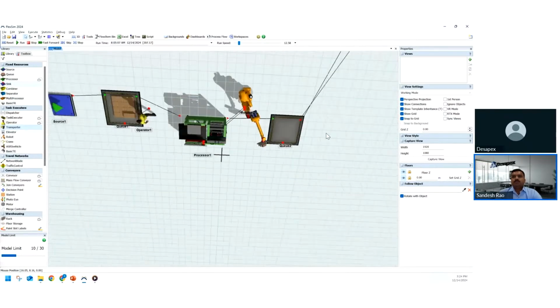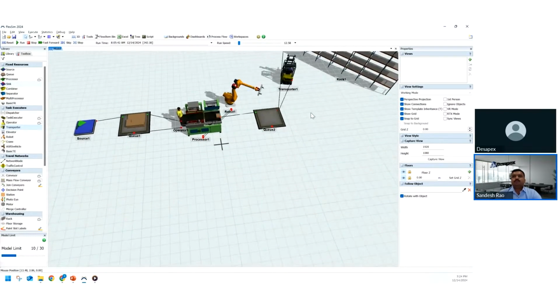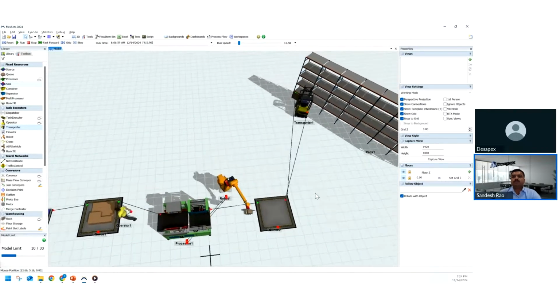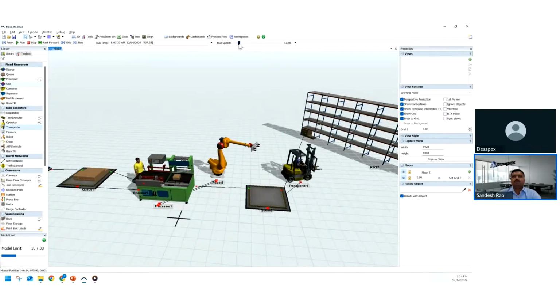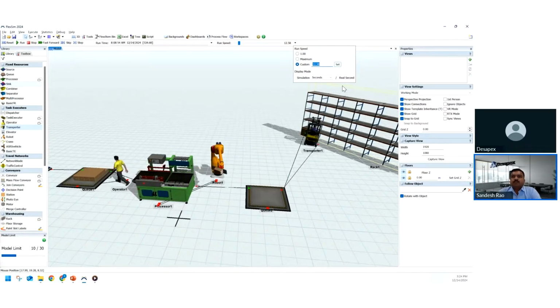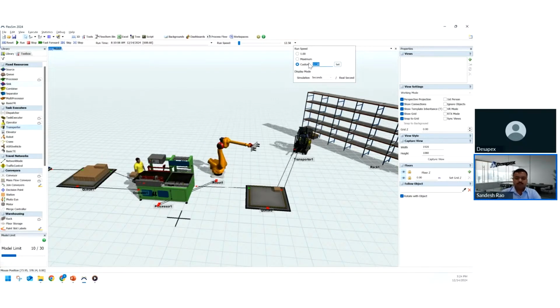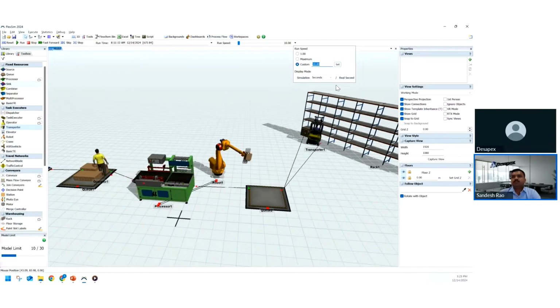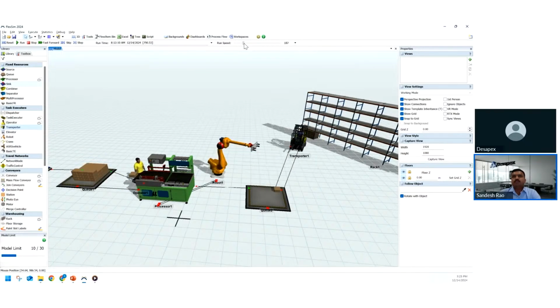So you may be wondering how much time it's going to take for us to look at how this is going to work. And that's where we need simulations, right? So when we do simulation, it is to create the real-time scenarios, but in lesser time. So what you see here, I can just set it to 10 seconds, which is actually in real time 1 second, but it is working equivalent to the 10 seconds period, and we can manually drag it and increase the time period. So we can see how within what time it's going to fill all the places.